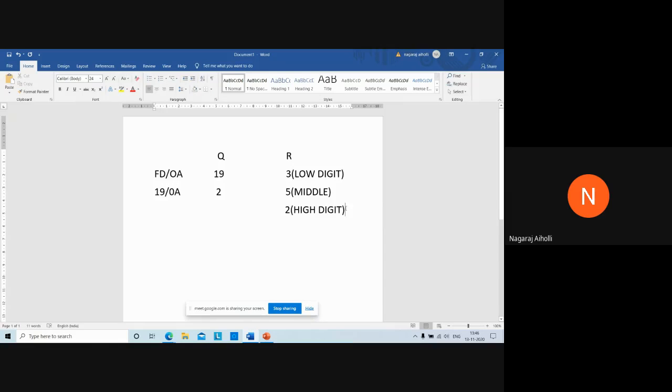253. You can keep your calculator in hexadecimal mode, right? Type FDH, then convert it into decimal. DEC, decimal, you will get FDH is equivalent to 253 in decimal. This is how you all have to convert it. This is the analyzing of the program. Is it clear?